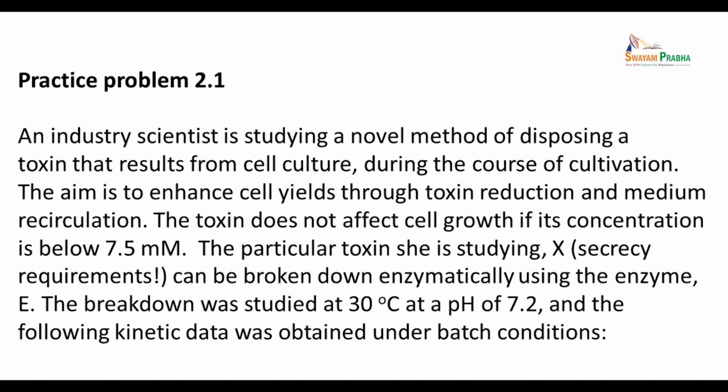Here it's a variation of enzyme volumetric rate with the substrate concentration. And then we also saw that we could find out Vm and Km from the data of substrate concentration with time variation from a batch system by using the Lineweaver-Burk plot. Now we'll use some of those concepts to solve this closed-ended problem. Please try it out, and of course in the next lecture I will show you how to solve this.